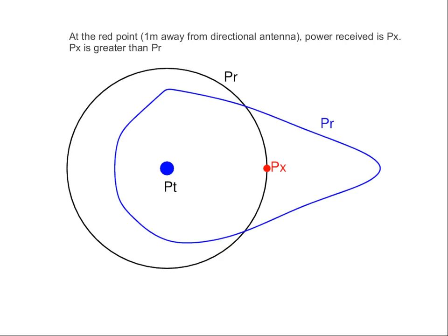This is antenna gain. And it's a common characteristic when you see an antenna or purchase an antenna, one of the properties in the specification will be the gain, which says that a gain of 2 says that this specific directional antenna in this one direction will have a power 2 times as strong as if you used an isotropic antenna.